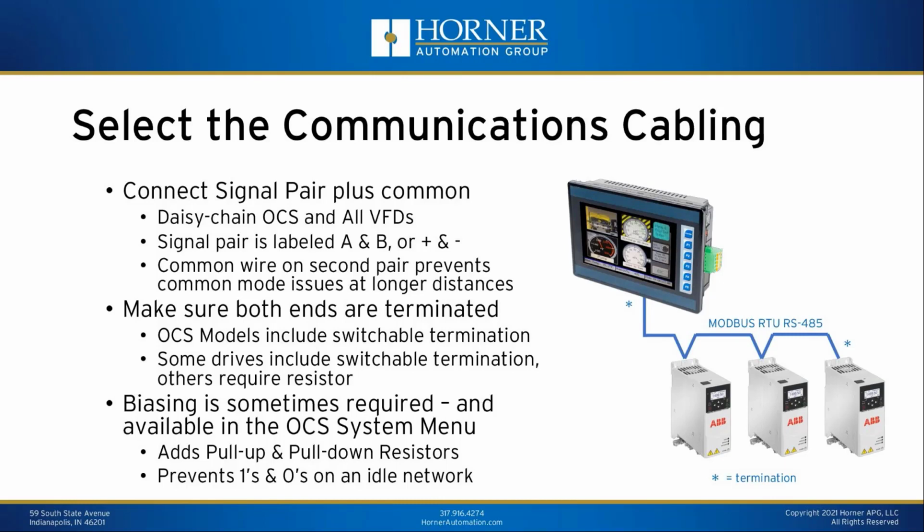Now, the way RS-485 half duplex works, and that's what you're going to find here with the Modbus RTU in almost every case, is that both devices are using the same pair of wires, that signal pair, to communicate. At any given time, either one device will be communicating, say the OCS, or the other device will be communicating, one of the drives, or neither if you're in between. Sometimes in that scenario where no device is communicating at any given instant, you can get some, I guess we'll call them spurious ones and zeros that may fly around from time to time when no device is driving the communication bus.